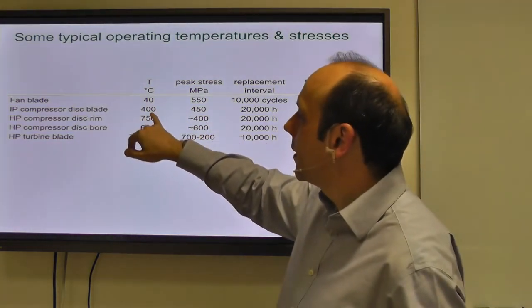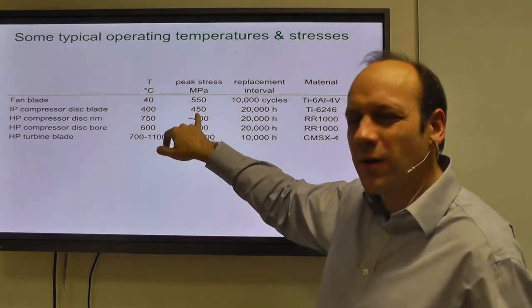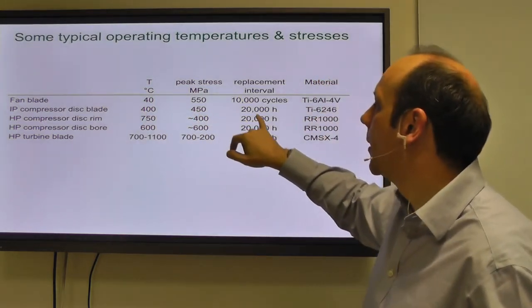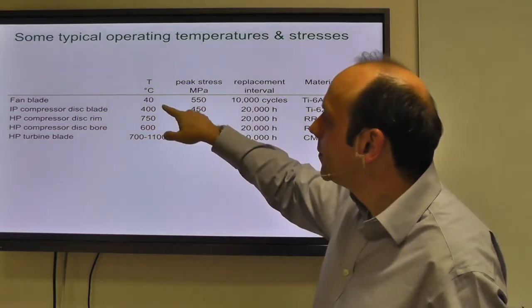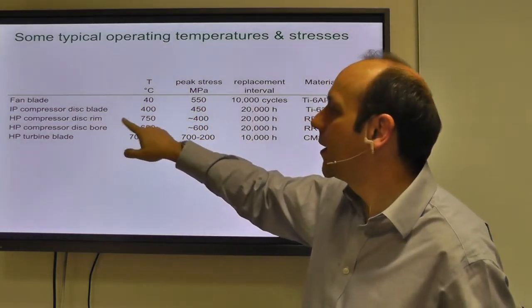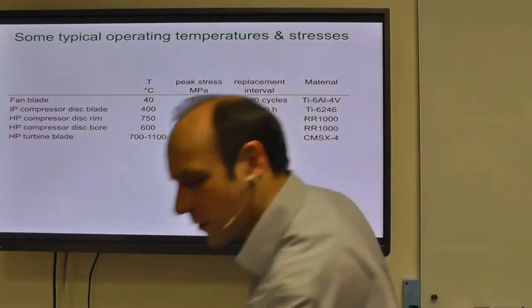Then as we come into the compressor, we'll get hotter. The stresses will probably drop a little bit, but not much. And they'll last again 10, 20,000 hours, slightly depends. Then we go to the disc that blade is hanging off. Actually, we go a bit further in. We're then at the HP.